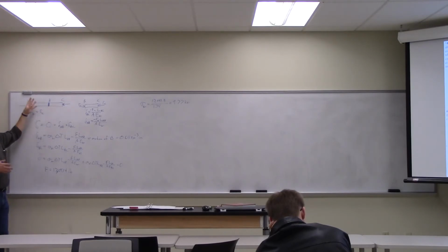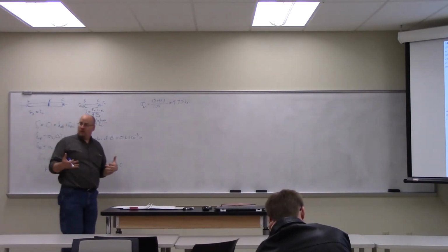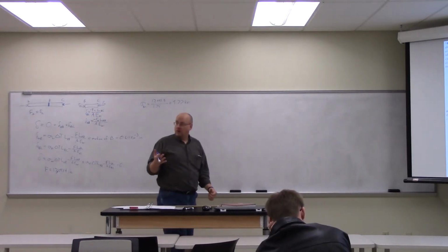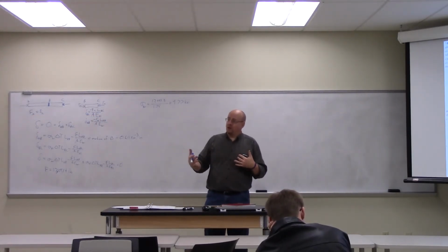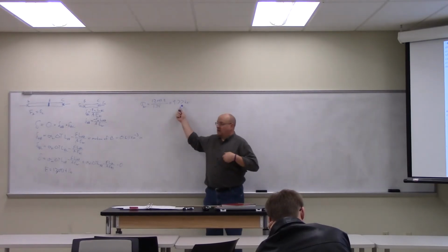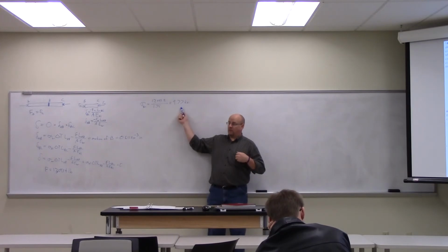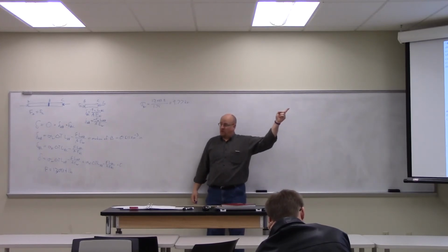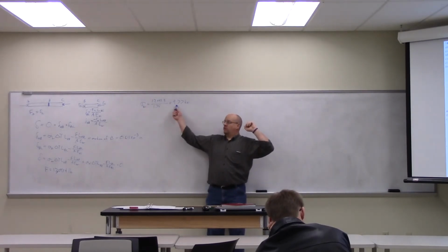That would be considered a state of residual tension, a leftover stress, because it had yielded along the way. So that's why it's important to check whether this is enough to make it yield. That's only a 70-degree temperature change, a pretty small change, and yet even then it's got very close to a yield stress.